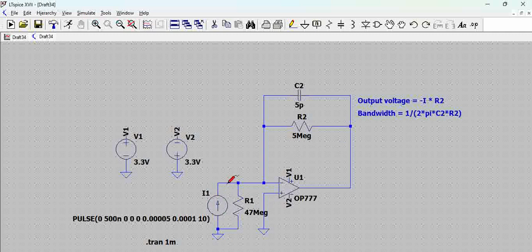We can also include the capacitance of this particular sensor, the trace capacitance of the PCB as well, and the pin capacitance. Anyway, pin capacitance will be part of the model. So all these can be included here along with the final capacitance, and we can actually simulate this to adjust the feedback resistor, capacitor, and the input resistor.